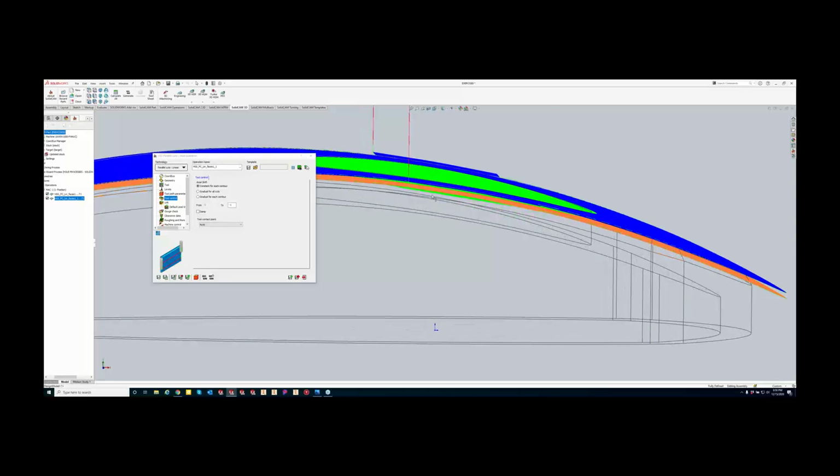It's hard for me to see, but yeah, like I said, we'll get into the actual shift when we start doing 3D chamfers, because that's a big thing that I want to cover with you guys as well, and probably on this exact same part. But if you guys are just looking to make that, like if you're doing a mold and you need to go a little bit deeper or shallower, I would definitely go to your geometry page and do a drive surface offset at that point. Because if we're going at a higher angle rate is where I think we would see the difference in that actual Z shift versus the drive surface. So,